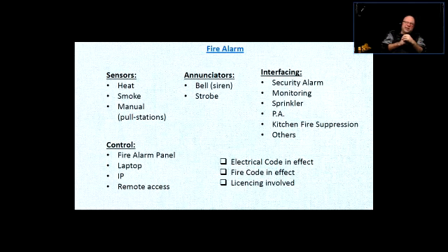interfacing sprinkler system. The other sprinkler system would be dry sprinkler systems, and that means that the pipes that are connected to the sprinkler heads, there is no water in them. Right? It's just air inside. And when the sprinkler head triggers, then the water is being released from the main sprinkler system panel, and it's just flooding. Now, why would we have dry or wet systems?